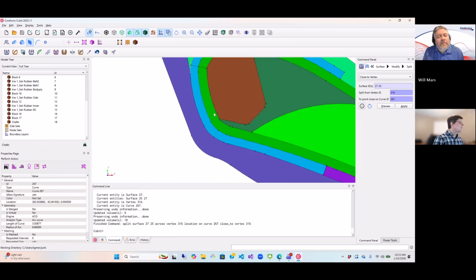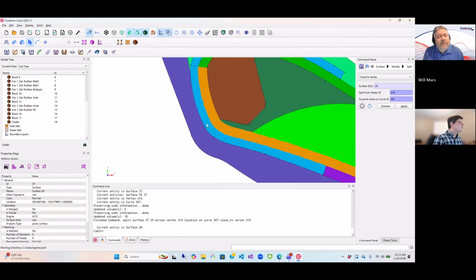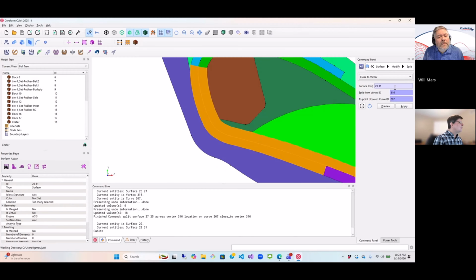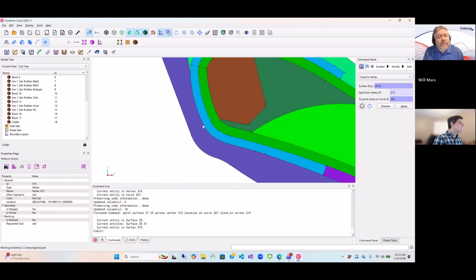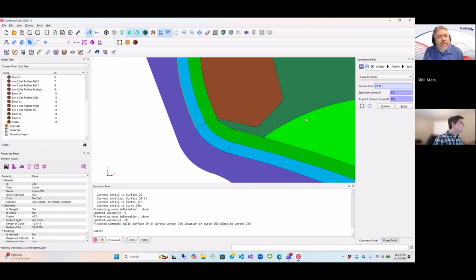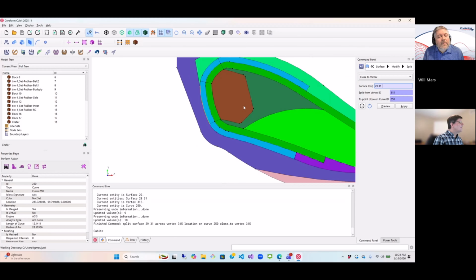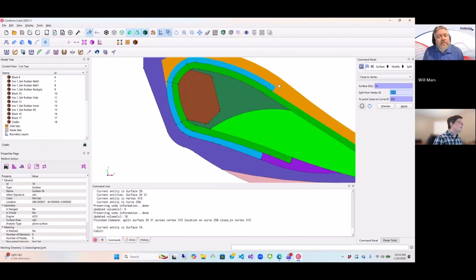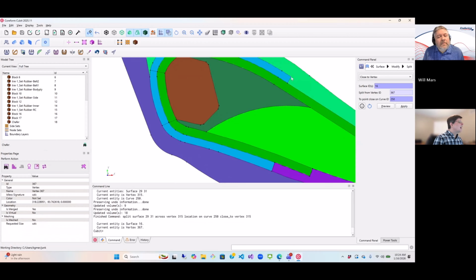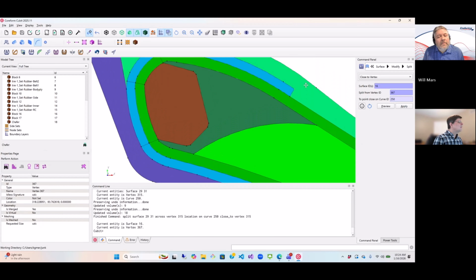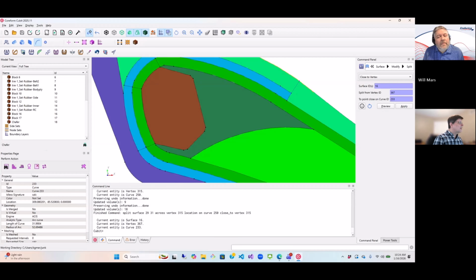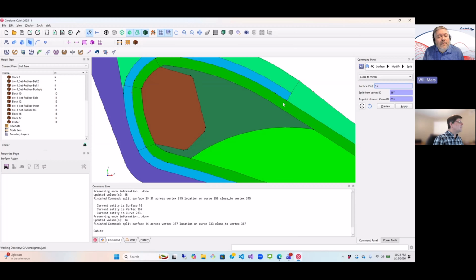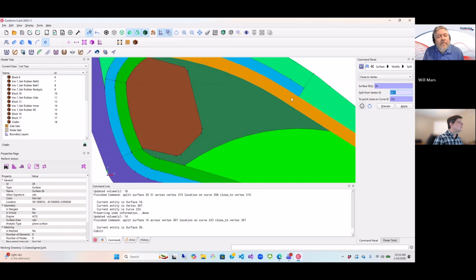Similarly, if I say, okay, let's cut from these two surfaces, notice that the focus was already in that top one. Middle mouse button there, and a curve over here. All right, Alt-A. Okay, so we insert some things there. It's probably good to clean up this one as well, because we'll end up with high skew there if we don't. Let's preview that. Yep, that's right. So you can preview at any time to make sure that you've got the right things.